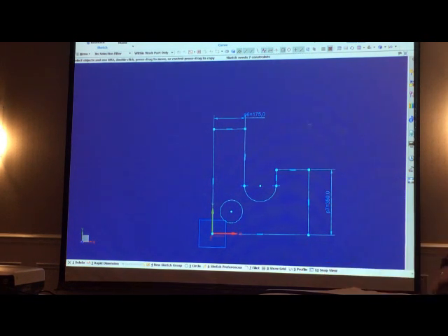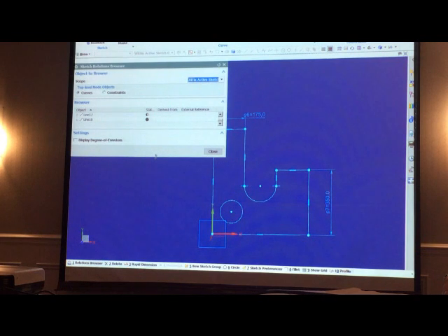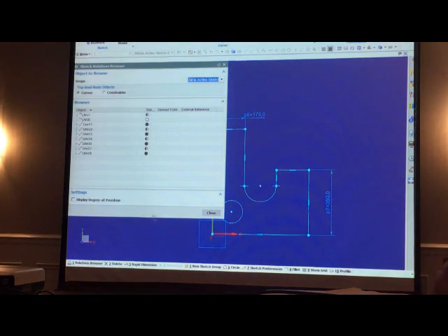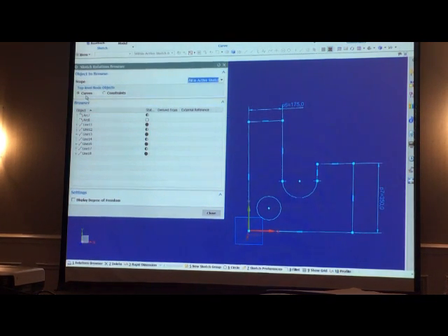So these are things. Now we also have a relationship browser in here. This replaces the old dialogue that used to be where you would go to edit and delete expressions and so forth. So now what we have is constraints. Now I can list by curves, and you can see which ones are constrained, which ones are fully constrained, under constrained, or this one, which is this arc right here, has got no constraints on it at all. So that's why it's an empty circle.